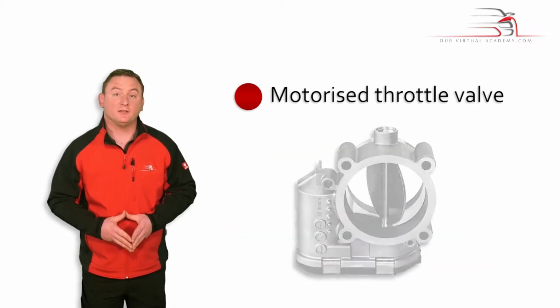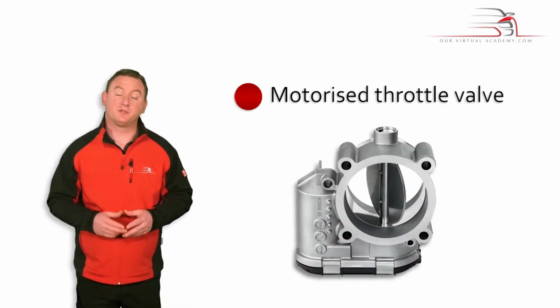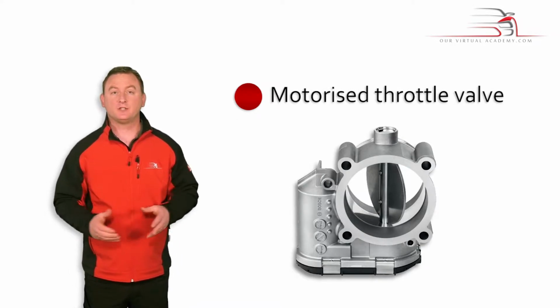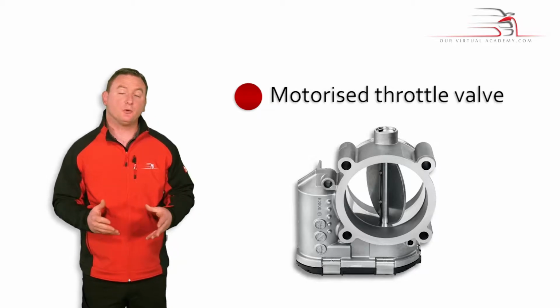Yes, exactly, well done. It's the motorized throttle valve which is controlled by PWM, as the other components are sensors rather than actuators, and PWM is used to control things that do work. So in terms of work, what do we mean by that? Well, by work, I mean components that actually do something. As a general rule, they'll be controlled by battery voltage rather than 5 volts like sensors tend to be. And they will either move, make a noise, or heat up.